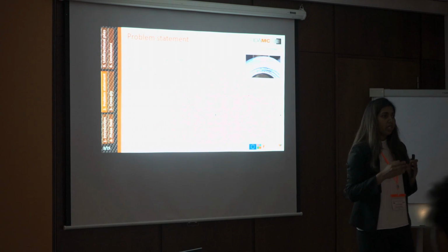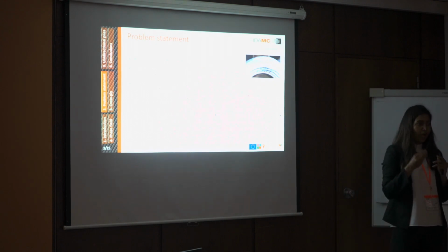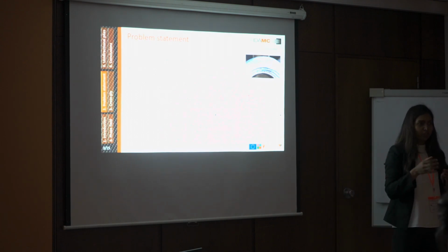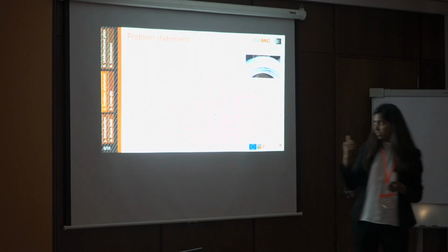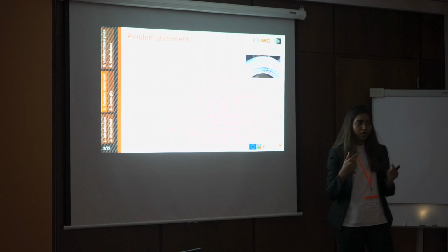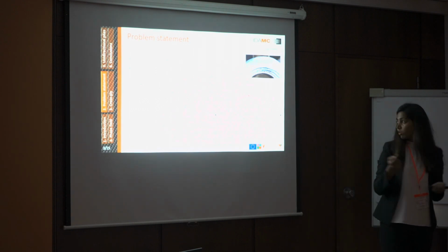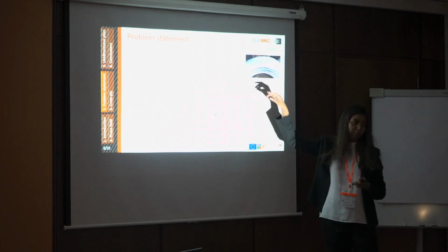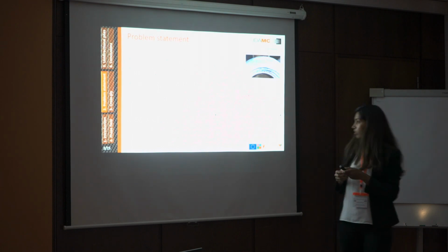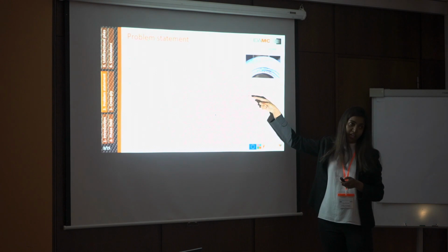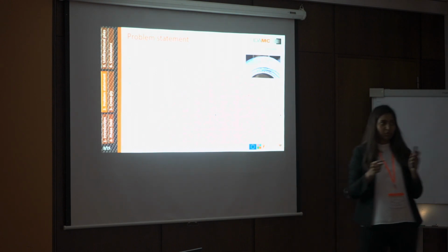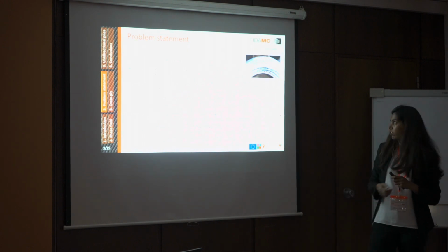Now, in the case of flat laminates, you have to provide additional loading to transfer this intralaminar crack to interlaminar delamination. But in our case, the curved composite specimens, we do not need any additional loading, because the curvature itself serves as a medium of high stresses. So this is a schematic representation. Here we can see that the transverse crack is perpendicular. I'm going to show the result, which is different from the perpendicular transverse crack.